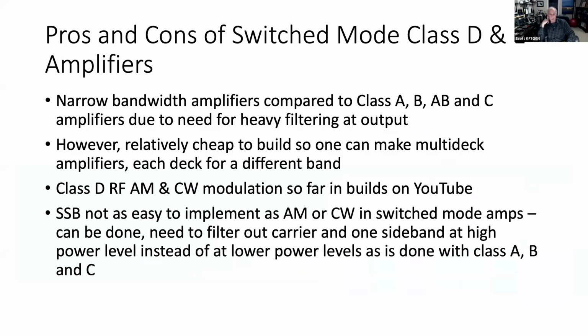They're very narrow bandwidth amplifiers compared to the other types that we commonly use today. That's due to the fact that you have to filter so much to get rid of all that ripple and digital noise that's sort of inherent in that sinusoidal signal. And in order to put the signal out on the air, you can imagine you can't have any of that, or almost hardly any of that, left in your final output signal.